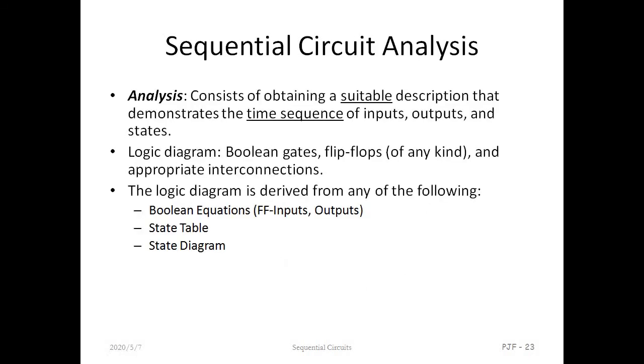The sequential circuit analysis. Basic analysis consists of obtaining a suitable description that demonstrates the time sequence of the input and the output states. Consider the logic diagram, Boolean gates, flip flops of any kind, SR, JK, D or T, and the appropriate interconnection. And third, the sequential circuit analysis is derived from the logic diagram through the following: Boolean equation, flip flop input, state table and state diagram.